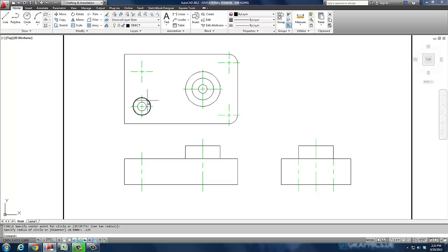If we look at a couple things though, I've got 2 concentric circles here, I should have 2 here. These center marks mark the center of this radius here and the center radius here. These mark these concentric arcs here. So what I'm going to do is copy my first 2 circles I did, those 2, from the midpoint right here, this is the very center of that circle, to the very center of that intersection right there. There they are. Now here, I know that if I project straight down, it is that line right there. So that tells me what that is. That's not a problem.